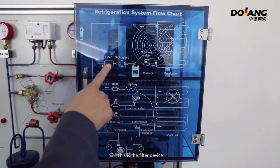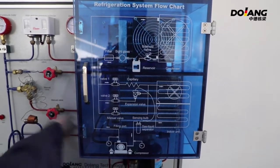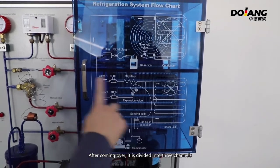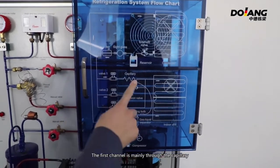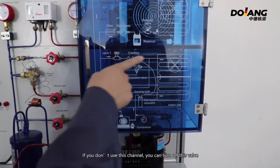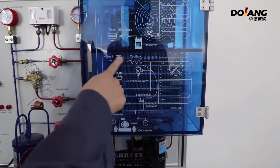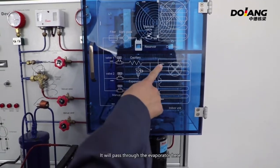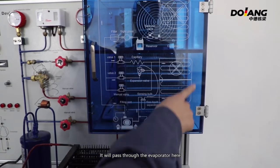This is the filter device. After coming over, it is divided into 3 channels. The first channel is mainly through the capillary. If you don't use this channel, you can turn off this valve. The following are the same. It will pass through the evaporator here.